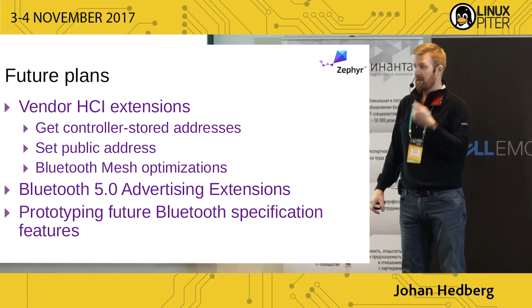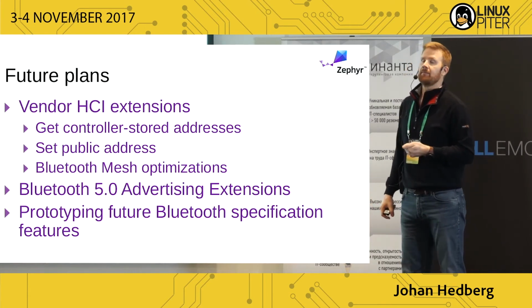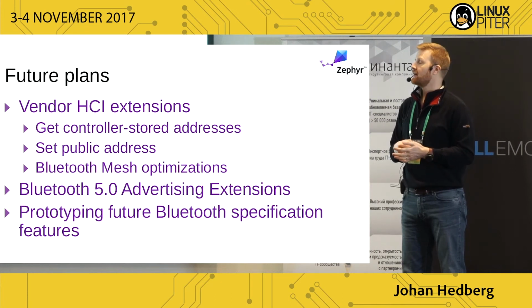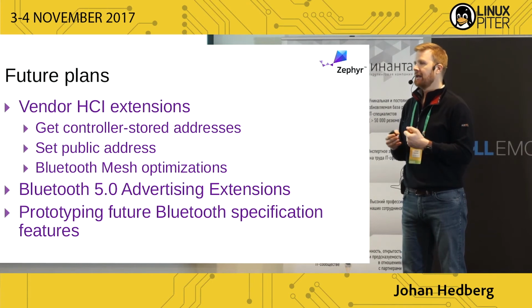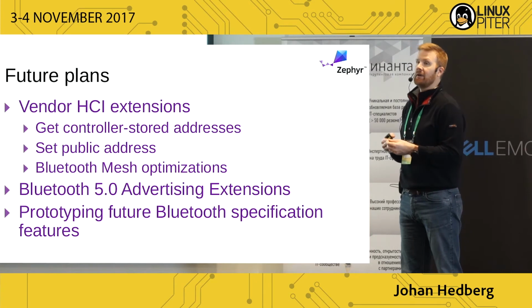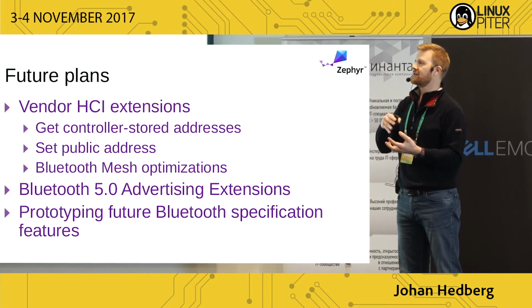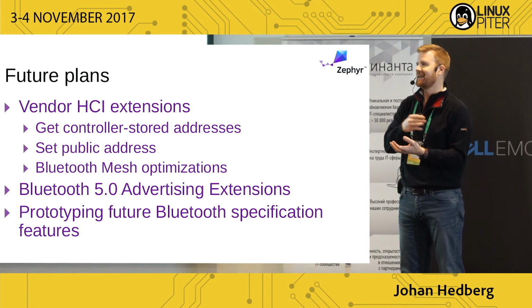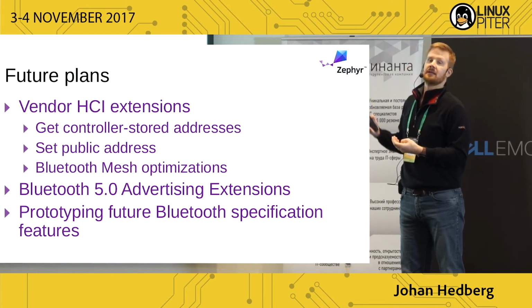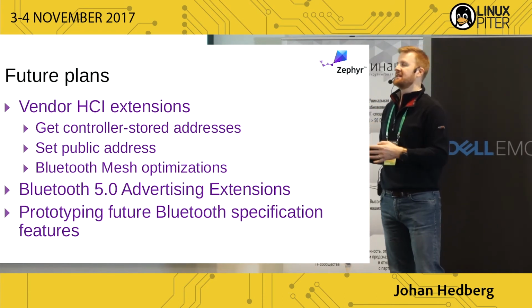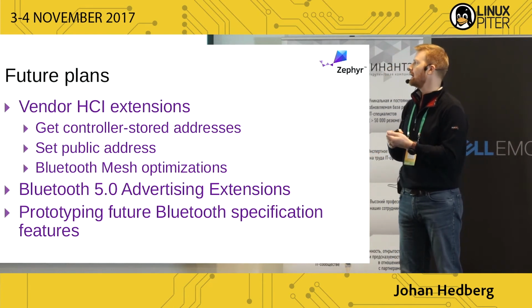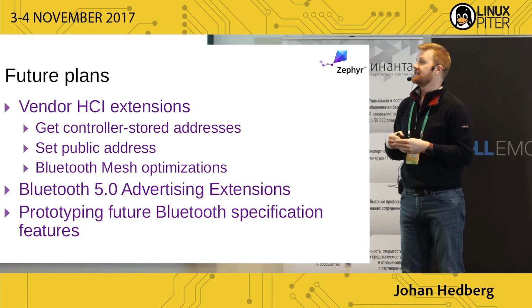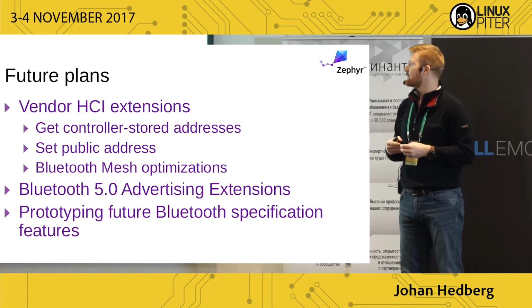For Bluetooth Mesh, as I mentioned in my earlier mesh talk, the standard HCI doesn't let you do as tight timings as the mesh specification would allow you to do. So you would either need to have a single chip system with no HCI there, so you can do exactly what you want, or what we are doing is extending with a couple of vendor-specific HCI commands where you can get exactly the tightest possible mesh friendship timings that you can have.